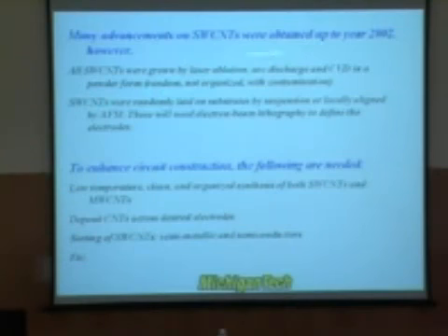In order for some of the devices that I showed you to be constructed, you have to use some of these random tubes and disperse them on the substrate by suspension, and then put it inside the electron microscope and find the tubes, and then lay down your electrode one by one, which might take a few days to make just one device. Or you can use the AFM to align your tubes to the position that you want, which is very time consuming.